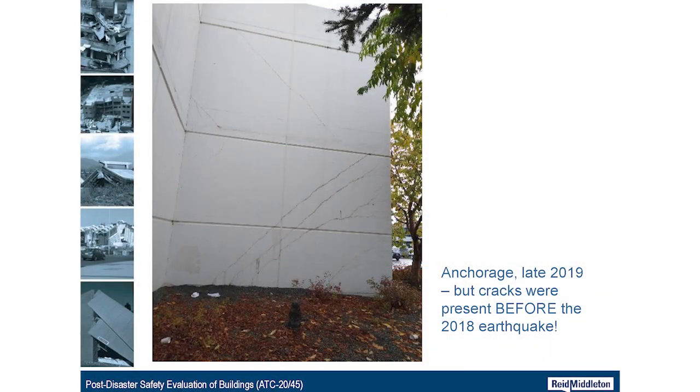Here's another example from the Anchorage earthquake from late 2019, where there's a bunch of questions about cracking. Apparently our team, I wasn't there personally, looked up some of the photos and even looked in the cracks, and there's a bunch of debris, and it basically became evident that those cracks were there before the event. So one tool in your tool belt is really getting into the nitty-gritty of the cracks and seeing if there's moss forming and weeds growing out of it or debris. And in some instances, owners of buildings might be concerned about a crack that actually was there beforehand.